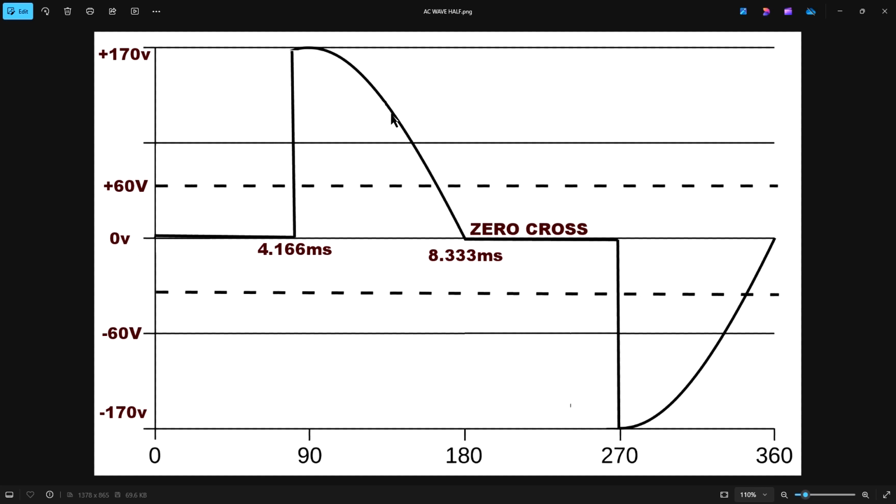We can come along here and turn it on here, maybe right here, and get, say, a fifth of the power or a tenth of the power, or we can increase this up to where we turn it on very quickly after the cycle starts and we get most of our current, or our power, but not all of it. So we just dim the light just a little bit. So these are very handy circuits.